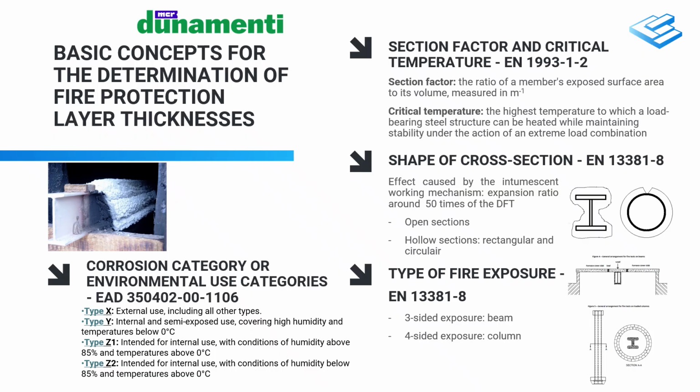On an open section such as an I-beam, this process occurs without any issue. The foam expands parallel to the flanges and surrounds the section. However, with hollow sections, particularly the circular ones, this effect can cause a lot of problems. Since the paint particles originating from the original diameter of the circle must cover a larger diameter as a result of the foaming. Imagine that, and also you can look at that little drawing. So the foam can crack up during one phase of the foaming process.